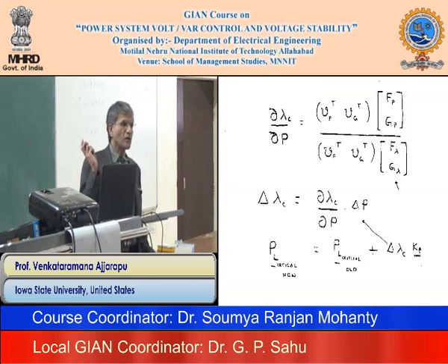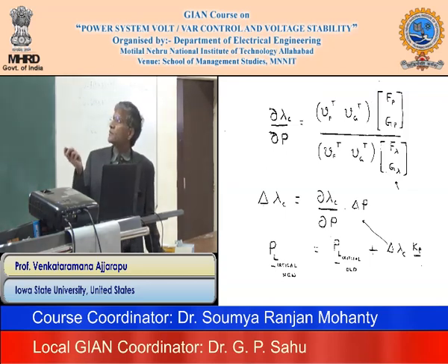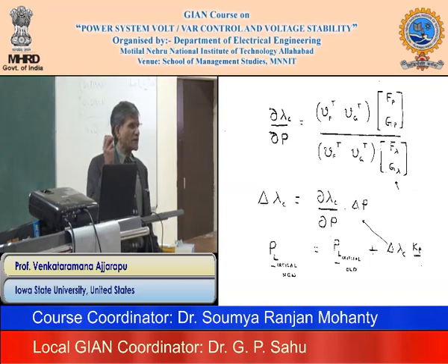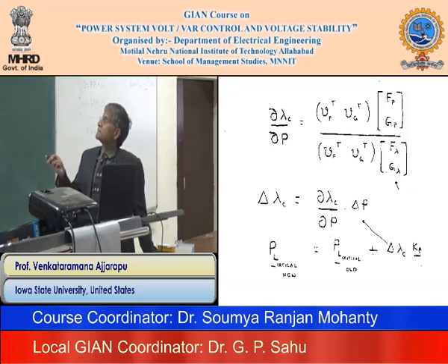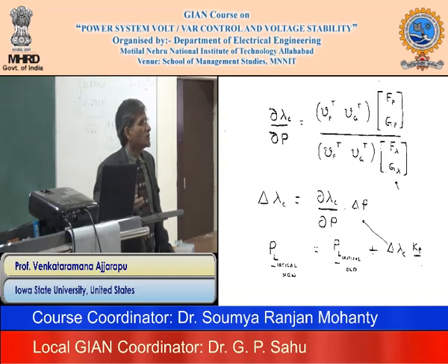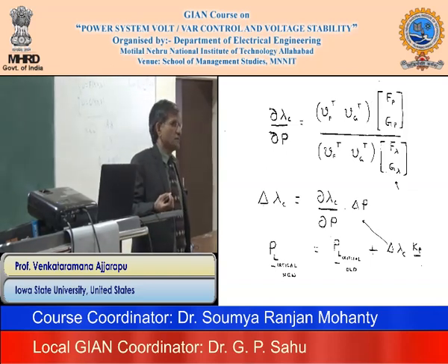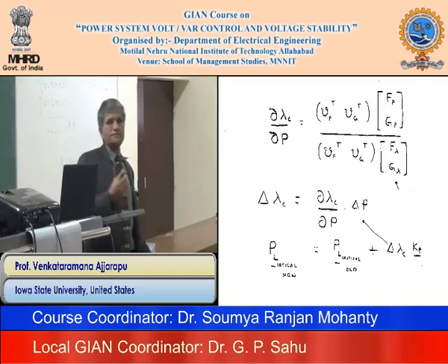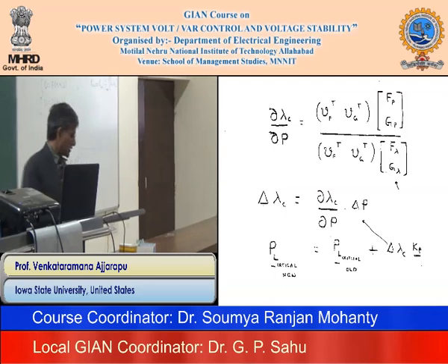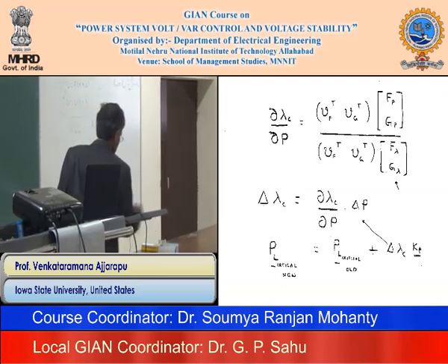So in my book, actually, we tried all the parameters. If you go back and look at margin sensitivity, we calculated for, I think, a 2 or 3 bus system, and see which parameters are basically affecting the margin. So indirectly you can also know for voltage stability margin improvement, at least locally, which parameters you can change to increase the margin. And when I talked in the morning with respect to this PV curve,